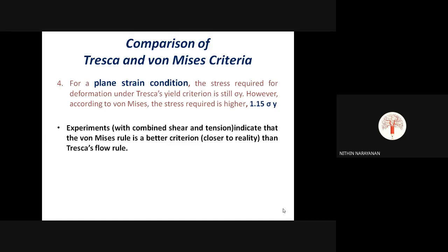Engineering stress strain curve and true stress strain curve. In the case of the true stress strain curve, we are taking the instantaneous area. Up to the elastic limit, Hooke's law is valid. Beyond the elastic limit, the flow curve equation is taken. Then, what is flow stress? And the different yield stress criteria.